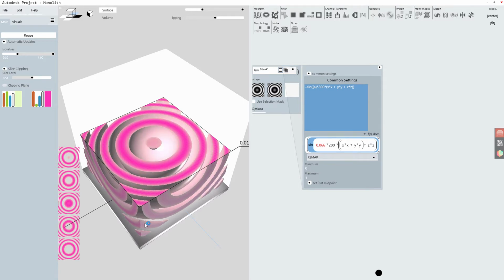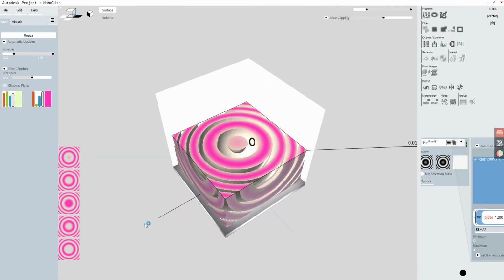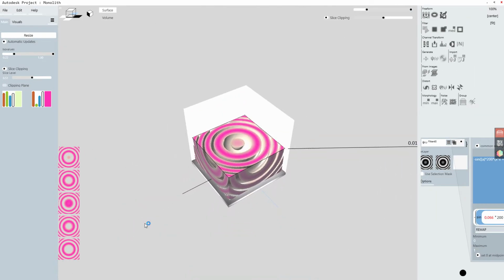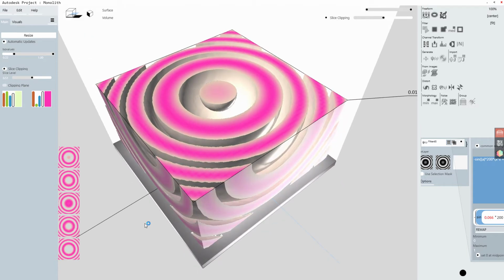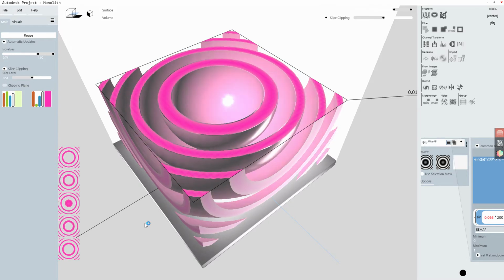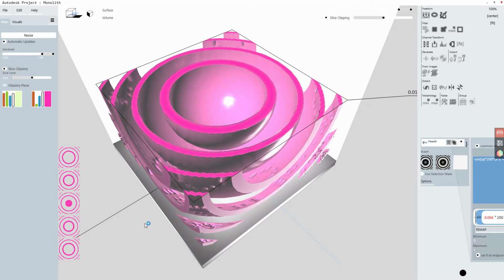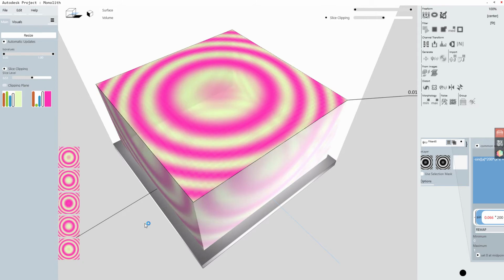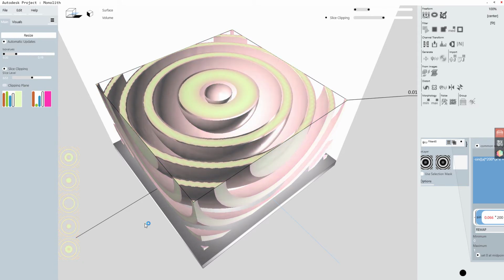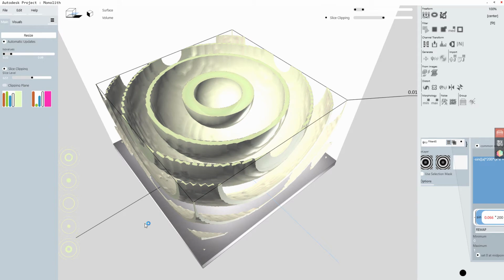What's interesting here is that if you put in sync the shape channel with the material ratio channel, you can see that the areas that are more pink are more dense in this object, and they're the ones that stay. If you put the bar in the dense areas, that is where the material is more dense, and if I go to the other end, that is where the shape channel and the material channel are the lowest.